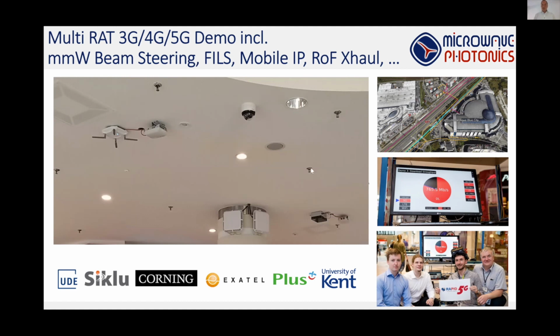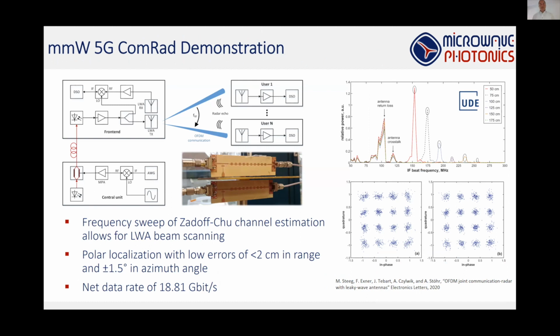And this was a development of a 5G station developed here by our university, which provided seamless beam steering using a special antenna technology. And it has a fiber optic front haul. So here we have a direct fiber optic front haul connected to the station, and then also beam steering used in this system. What is also interesting for 5G is that if we have beam steering, we have to have directive antennas, and this will be even more important for 6G when we go up to even higher frequencies. We need directive antennas.